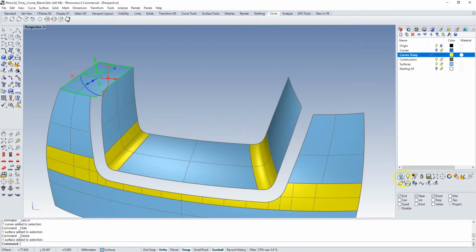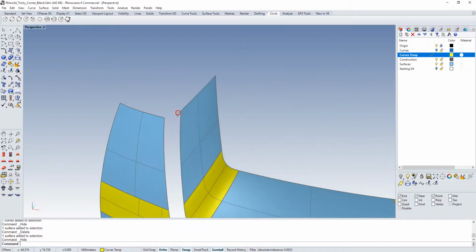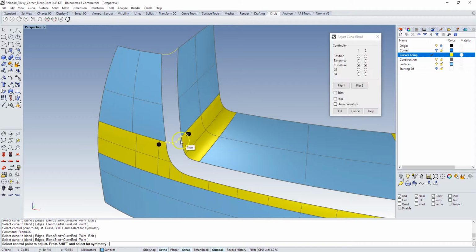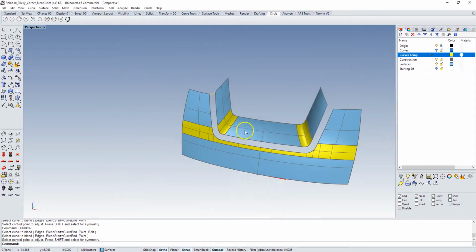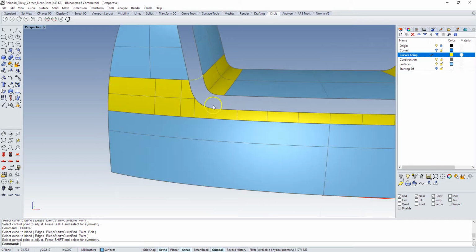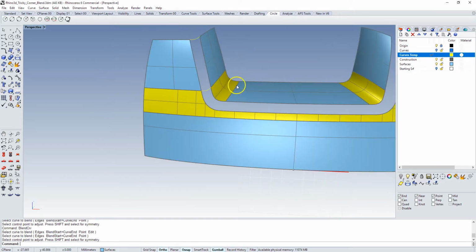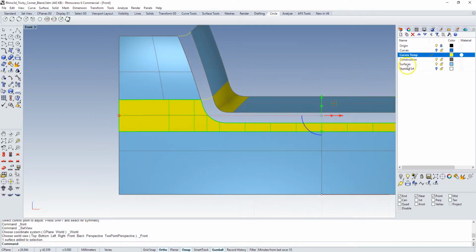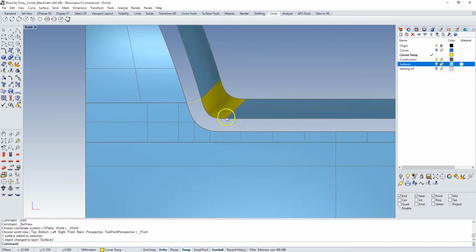I'm going to hide this for a second. So we're going to need some more blend curves, and from there to there, curvature, that's one. And then from there, I'm going to use the top edges in this case. There, accept that. And so now I want a blend curve to fill this square. And this is one contiguous edge because it was one surface and there's no split in it. But I want this edge to follow this edge. And so if I turn this to my front view really quick and change that to surfaces, change object layer so we can see it a little bit better.